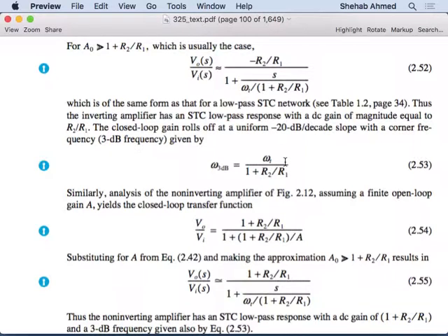Makes sense. Again, they're physical systems. You're passing a signal through them. You want to integrate it, or flip it with a gain, or just apply a gain. Is this gain going to be for infinite bandwidth? No, they will be frequency dependent. We saw that they were frequency dependent in chapter 1, in the last problem where you had a capacitor. We saw that there was some frequency dependence there, right? And this is where it comes from. This is the capacitor in chapter 1. We did not relate it back then, but this is the effect of that capacitor.